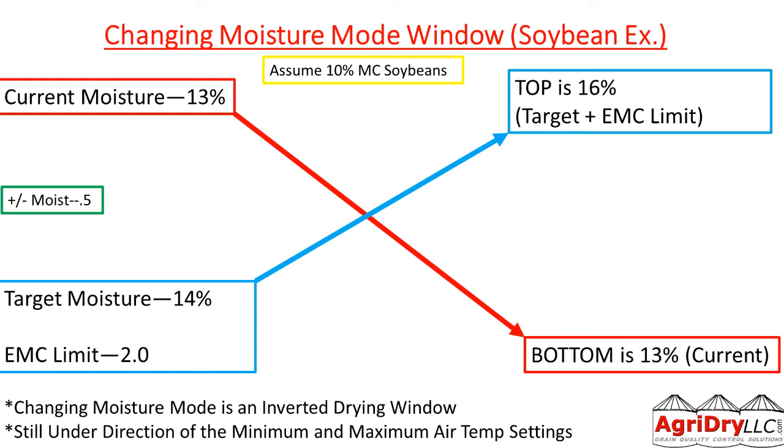The important thing to remember about moisturizing mode, you want to baseline your static pressure. Keep track of it. So if it ticks up a point, you can adjust your window, pull some grain out.